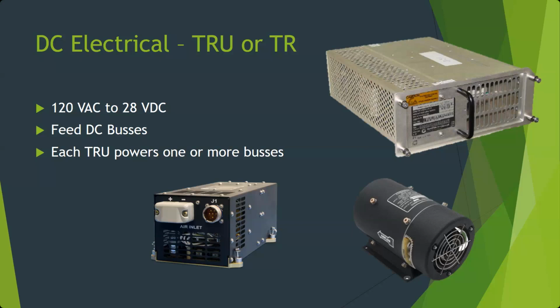The non-essential DC bus TRU, you could defer for like 10 days. It didn't have to work for 10 days. It could get power from somewhere else. So if you were somewhere where your backup emergency battery charger went bad, you could swap that with the good one from another location and get the airplane flying again. That's why they do it that way. Now instead of having a DC TRU on the shelf as well as a battery charger on the shelf, we just have one box sitting on the shelf that can go anywhere.